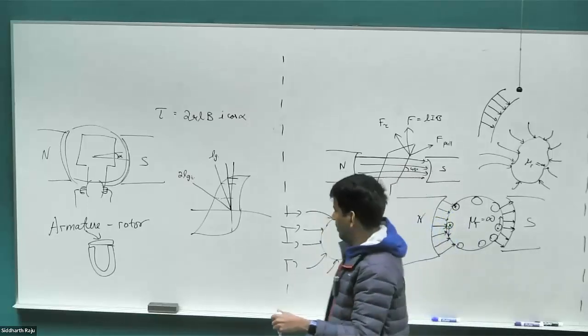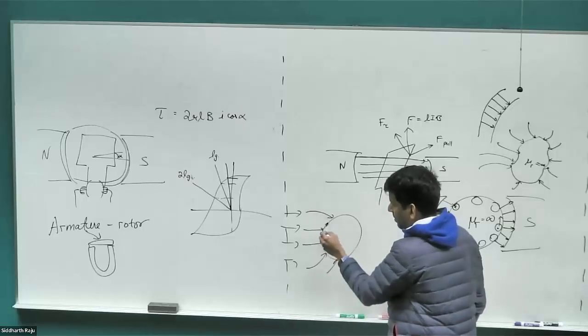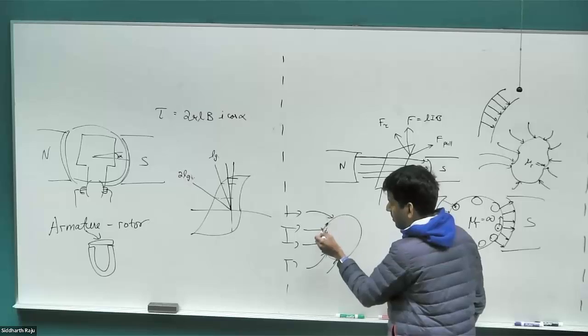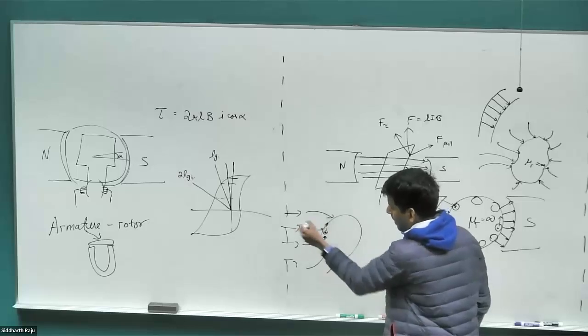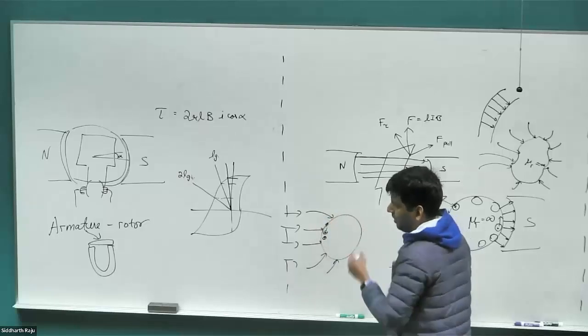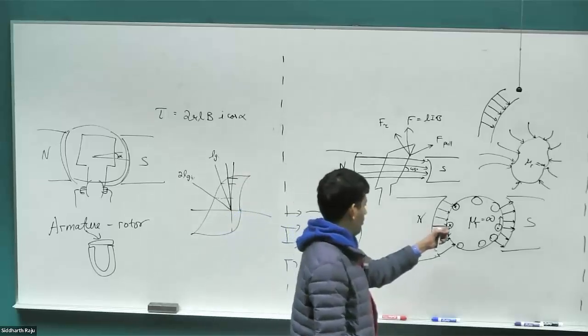If it is not terminating perpendicular to the sphere, there is going to be a tangential component, and the sphere being a conductive material is going to have a lot of free charge. The tangential component is going to pull the charges apart and spread them out so that only the perpendicular component exists. Otherwise, if there's a tangential component, it's going to create circulating currents. So that's how it gets eliminated there. You can do the same explanation here too.